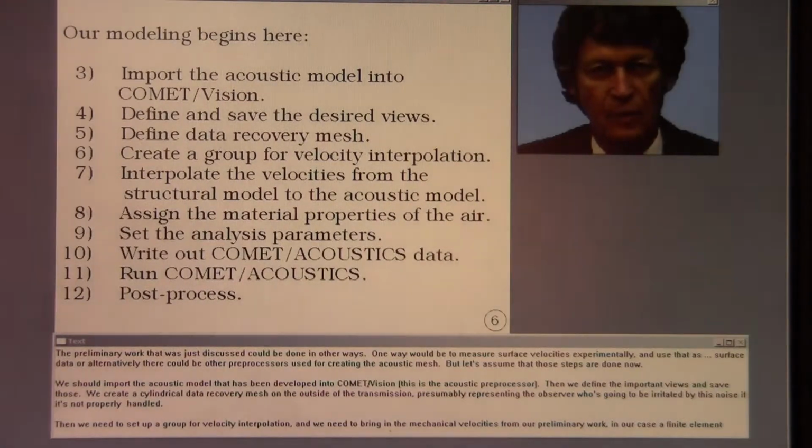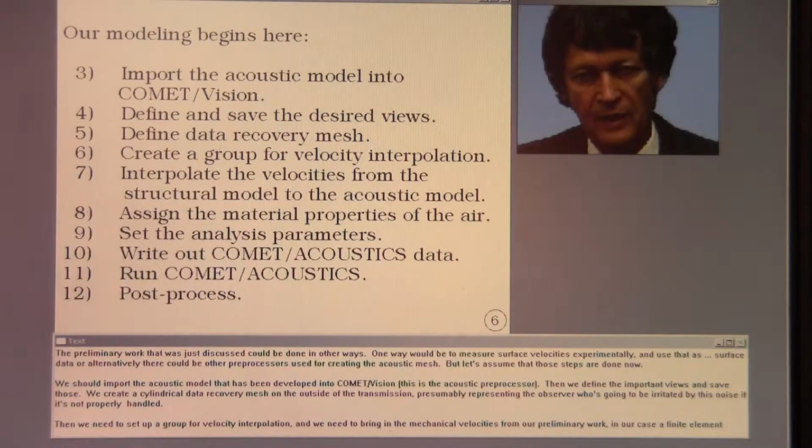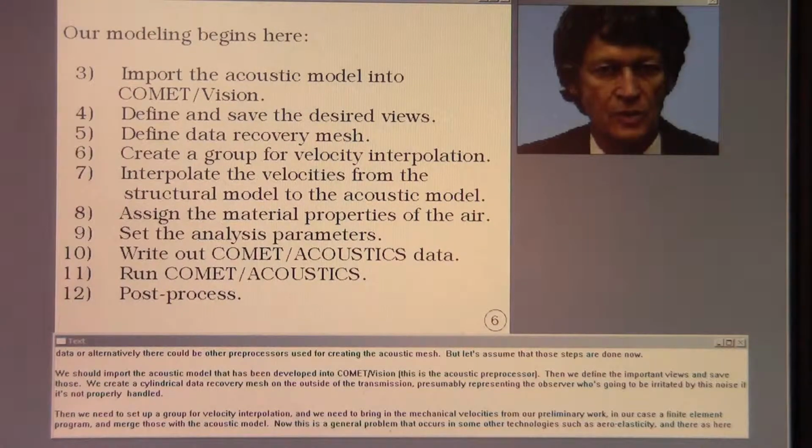The preliminary work that was just discussed could be done in other ways. One way would be to measure surface velocities experimentally and use that as surface data. Or alternatively, there could be other preprocessors used for creating the acoustic mesh. But let's assume that those steps are done now.